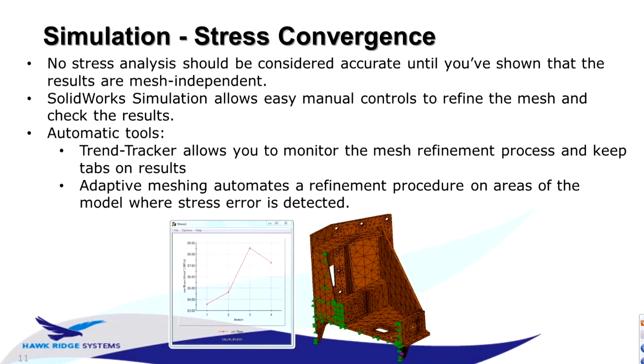Stress analysis, one of the most common things we have is, how do I know my result is accurate? And from a code integrity point of view, that code is very rigidly tested against a number of common scenarios, against these specific benchmarks, that if it doesn't give the right answer, it doesn't go out. Okay, but from a user perspective, one of the biggest controls you have over accuracy is the mesh grid that you've created.